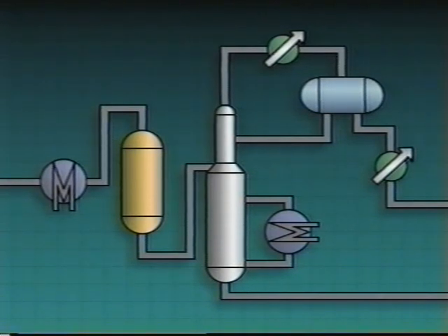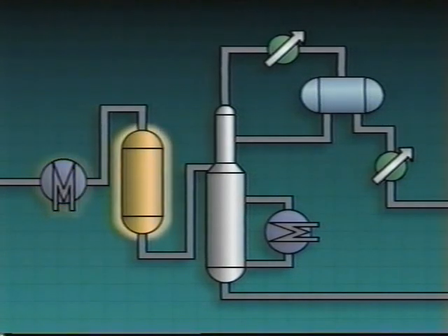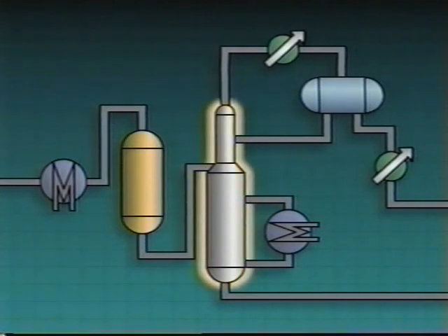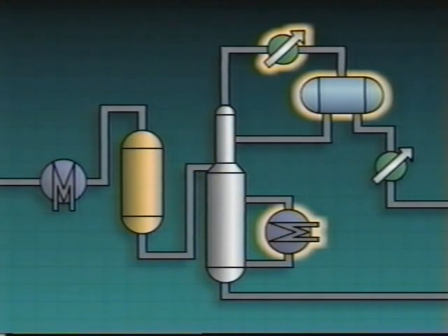Each of these possibilities can start a chain reaction of adverse effects that will get carried through the rest of the process. To locate the source of the problem, we can start at the beginning of the process and work toward the end, checking each component one at a time. Operating conditions should be normal until we reach the source of the problem. If, for example, there's a water leak in this condenser, the temperature, pressure, and other major process variables for the steam heater, the reactor, the distillation tower, and its equipment should be fairly normal.